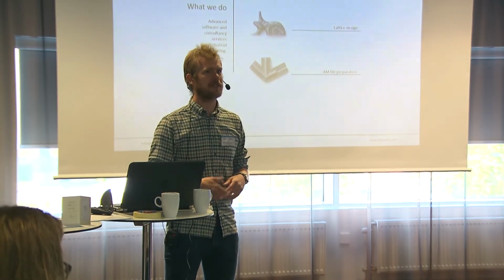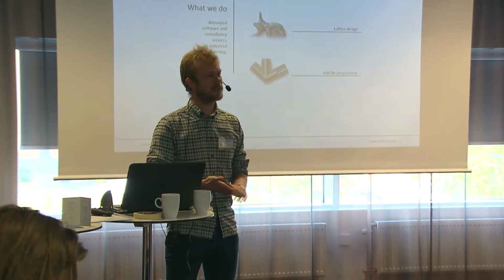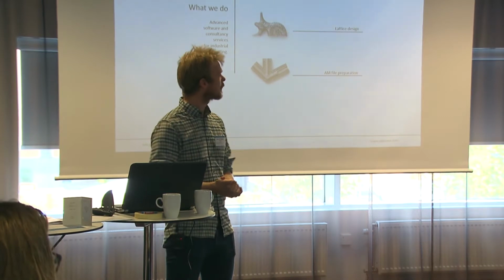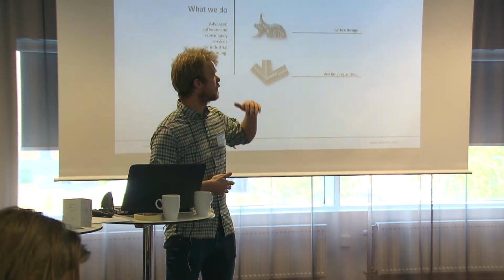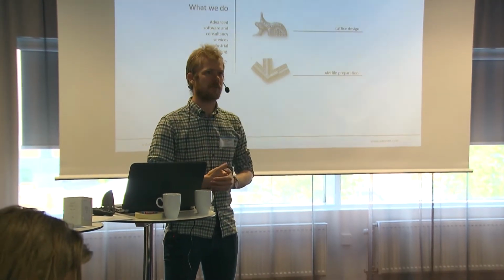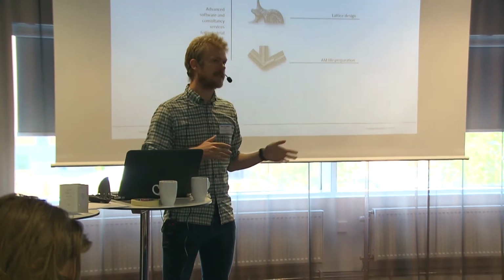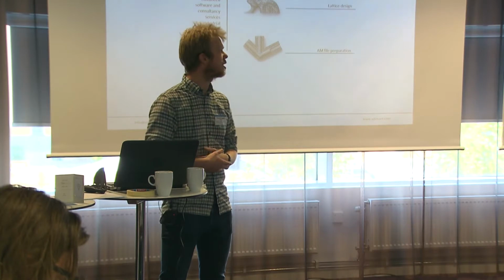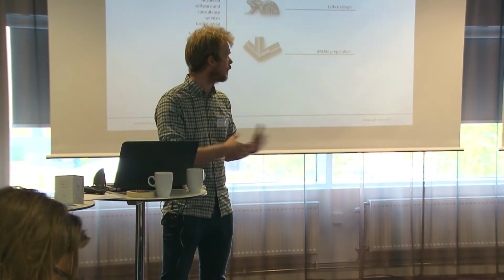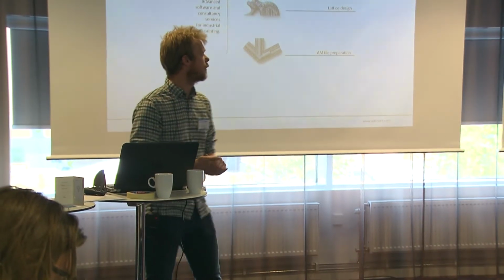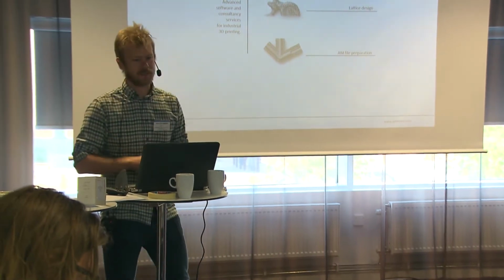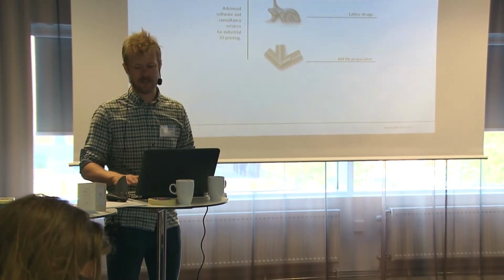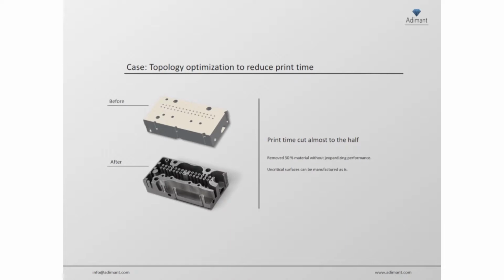Primarily customers in space and aerospace, because as Olaf said, cost and stuff like that. We help them with topology optimization, so doing it right. We help with lattice design structures when the lattices become really big, or if they need to optimize lattices for certain performances. And then we help them with file preparation, because it turns out slicing and hatching is a little bit more difficult than it looks like.